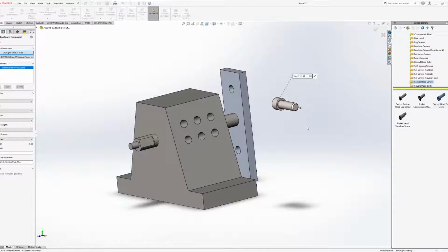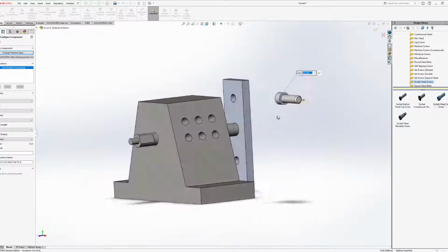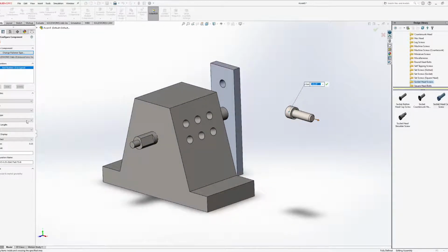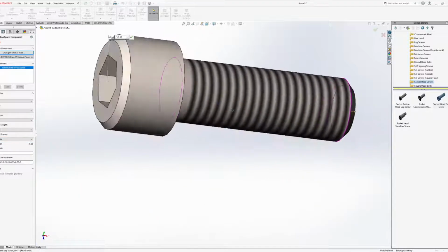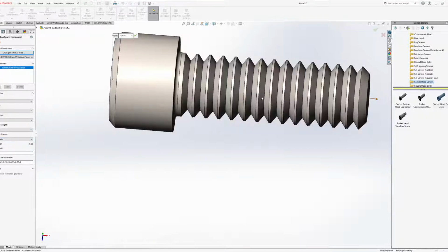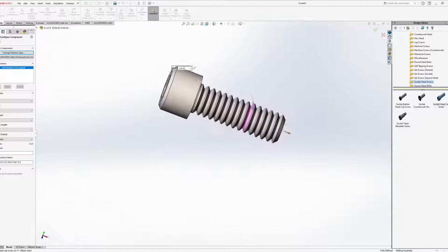I'm not really that concerned about that. Some of the details in the drawings might be a little bit more specific. I'll try to make sure that those things are coherent. On the left-hand side, you'll see that we can have a size drop-down menu as well, and we can also designate the length. This length is going to be in inches, and this size diameter is also going to be in inches. What's also cool is that we can use ones with a simplified, where it's just a totally smooth surface. You can give it a cosmetic thread, and probably my favorite, even though I don't really use it quite often, is you can use a realistic schematic thread.